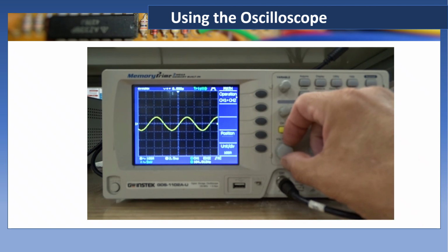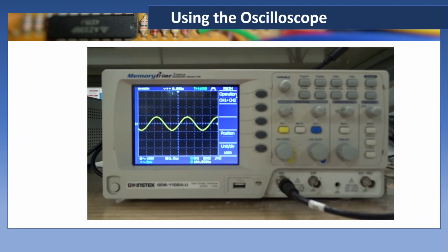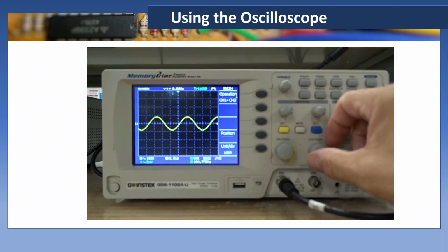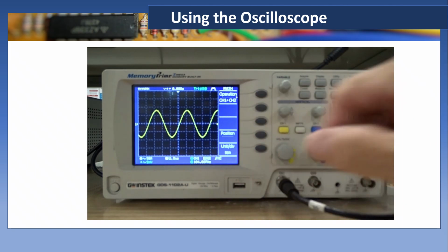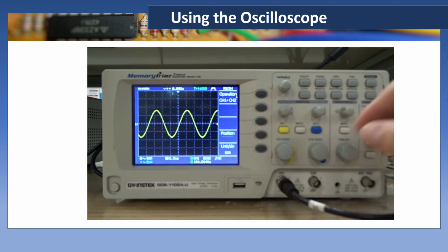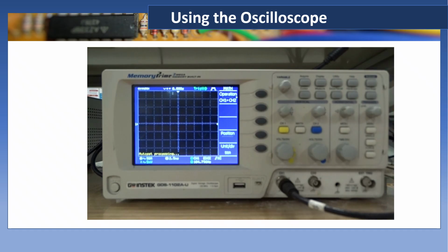So you want this to be about that size to watch what's going to happen when we put on a diode circuit to rectify the AC. Either that one or perhaps even we'll go up one higher, give it a nice sine wave. Now there's an auto reset button on the top, so when you first connect it up, you can give that a quick shot and it will recalibrate itself and give you the best overall picture.